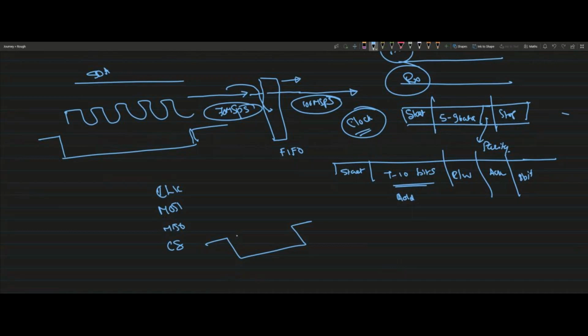So then what is the maximum number of slaves that we can connect? It depends on how many slaves you have, right? When I say slave, it can be ADCs or it can be DACs. So it depends on how many DACs, how many ADCs you have. For example, let me consider you have 10 ADCs, and you want to program these 10 ADCs as soon as possible. So you may design multiple parallel SPI masters which will be controlling these slaves, maybe 3-4 slaves at a time. So you have to design optimally based on your speed requirements. It's a trade-off actually.